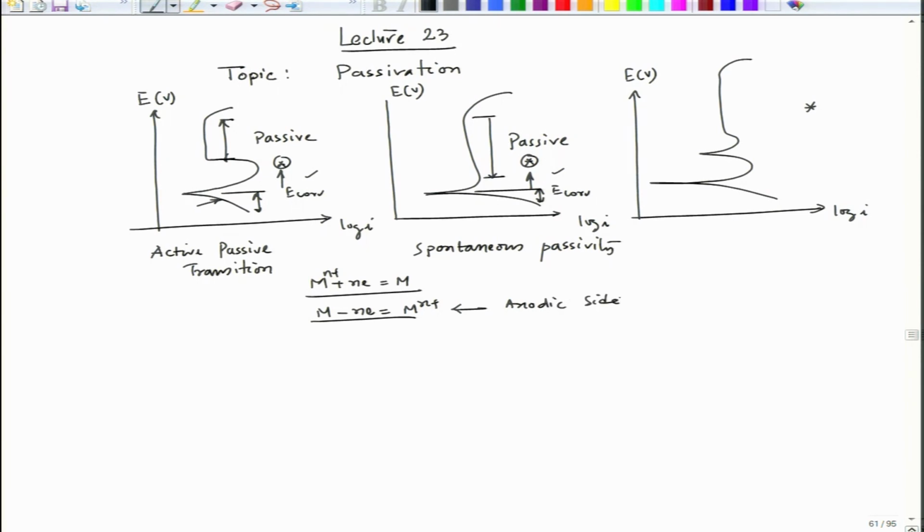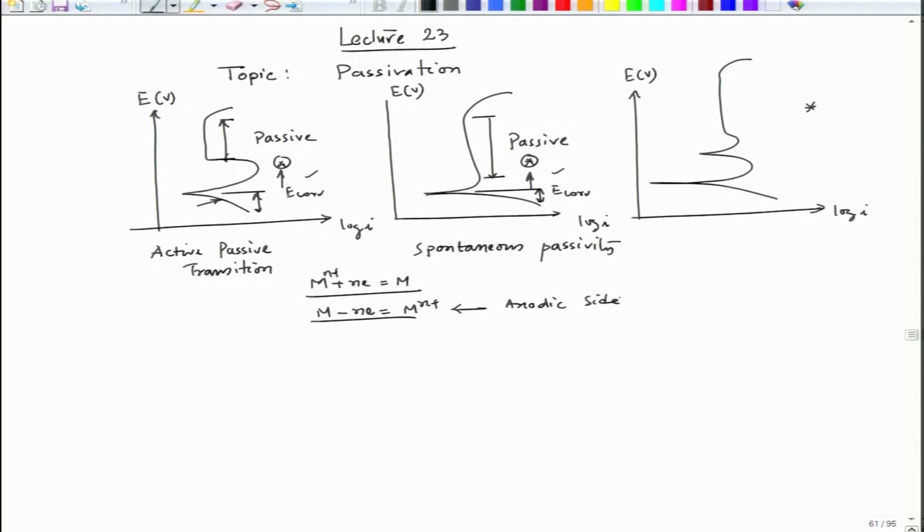This we talked about, and then we also defined passivity as basically chemical inertness introduced into the metal when that metal is exposed to an environment due to its ennoblement or anodic polarization. There could be some other instances like lead, where ennoblement or passivation appears because of lead sulphate formation in H2SO4. So, those cases we have considered.